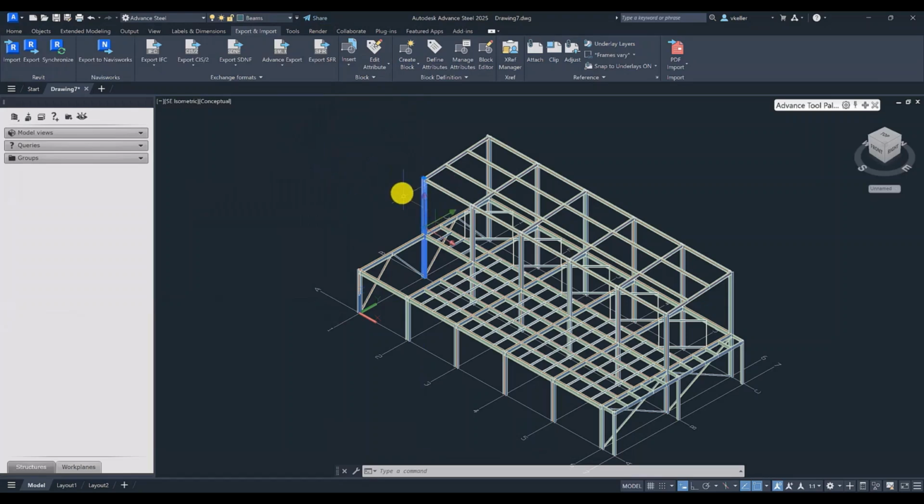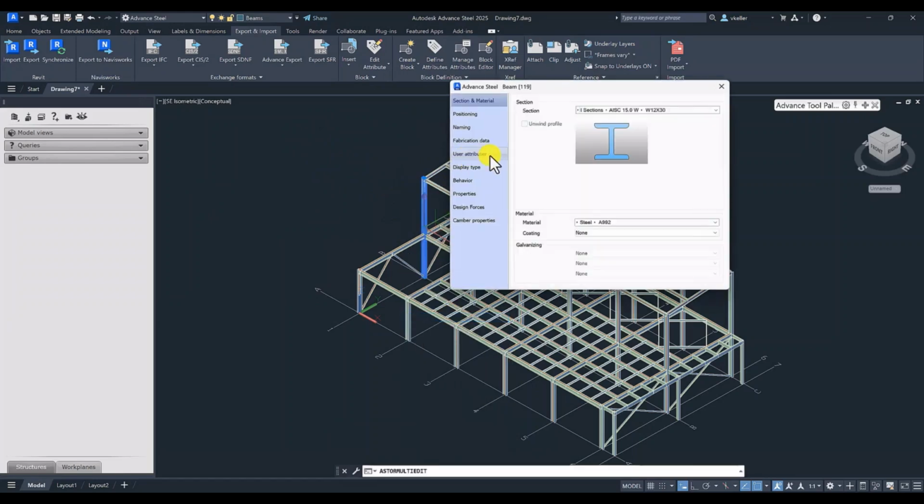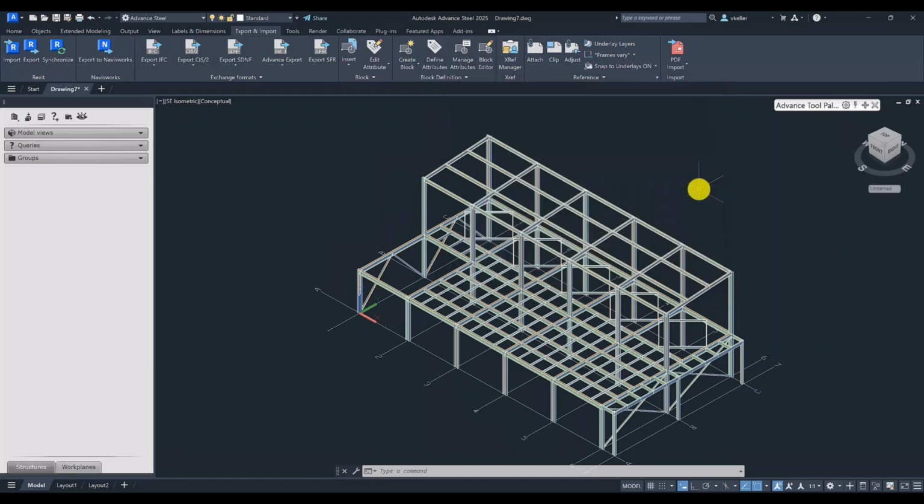So we can actually work together in the two software packages in this way, work back and forth. If I start something in Advanced Steel, I can do the same thing and bring it into Revit that way too, back and forth. It just depends on who started the project and what's going on. The typical thing I've seen a lot done these days is to start in Revit, get all the framing done, get that all squared away, because it's nice how that model's in there. Then I bring it inside of Advanced Steel, and then I can even put all my connections in here or in Revit, but I like to work with the connections in Advanced Steel and then push out to fabrication drawings.